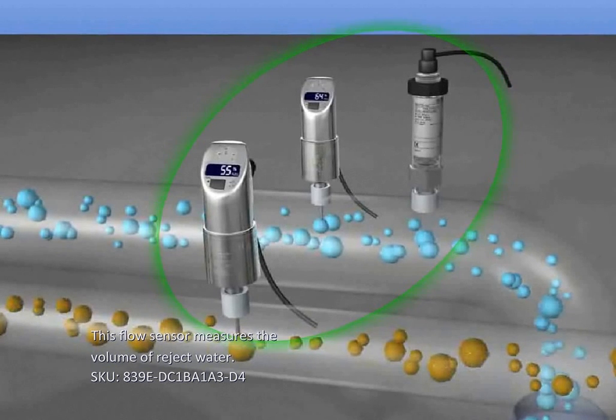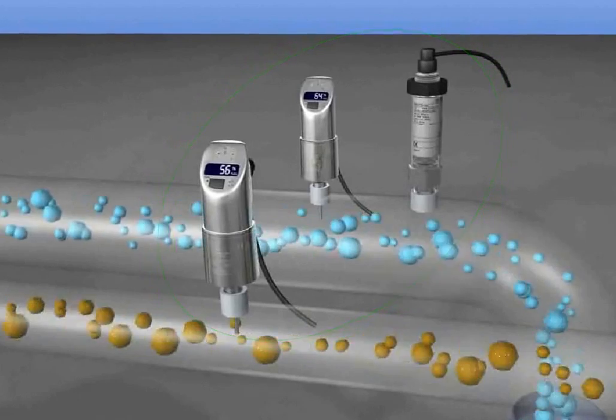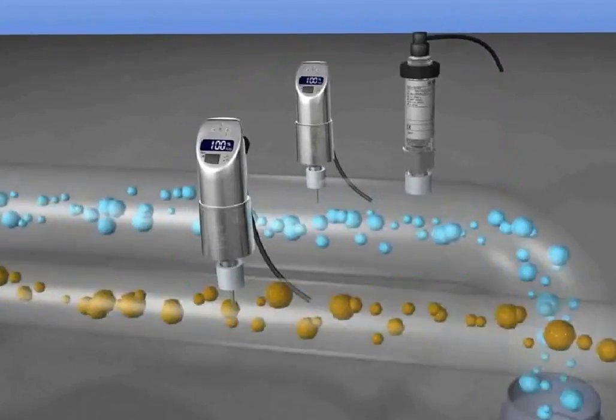The flow sensors display 100% when there is maximum flow through the pipes. A lower percentage is used as an indication of decreased throughput at the output end of the system. We are also using an 836E non-display pressure transmitter to check the water pressure at the permeate water pipe. A decrease in pressure indicates when the filters are getting plugged, and that it's time to backflush the filtration membranes.